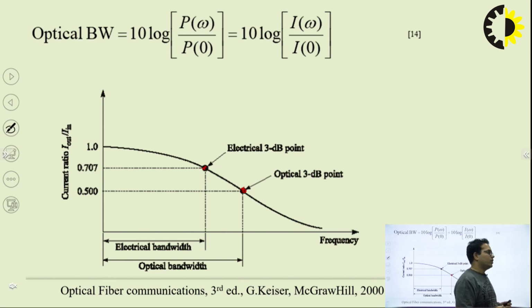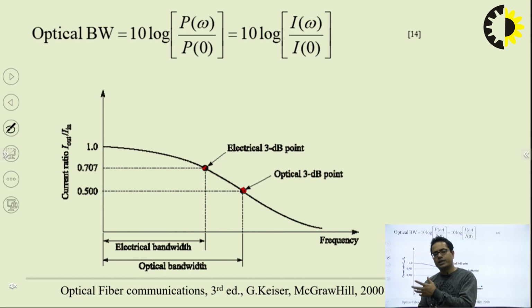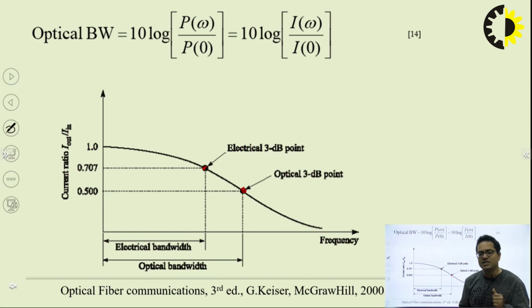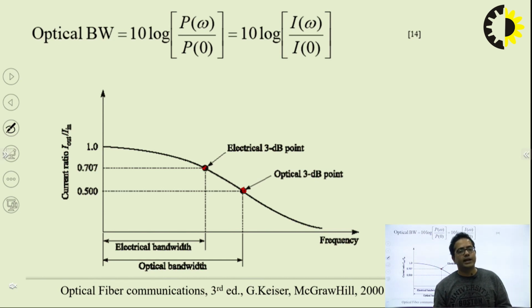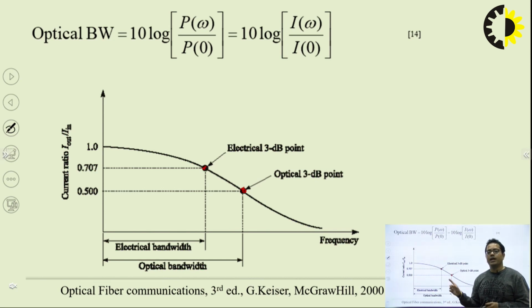This phenomenon is responsible for the LED. We also discussed the important requirements of optical communications, so that a particular source can fall under the category of a good LED or a good laser. We have discussed various criteria. Then we discussed the main difference between LEDs and lasers. LED is non-coherent, laser is coherent. This important criterion makes the laser highly directional. If a laser source is highly directional, it can efficiently couple light into optical fibers, especially into the single mode fiber.